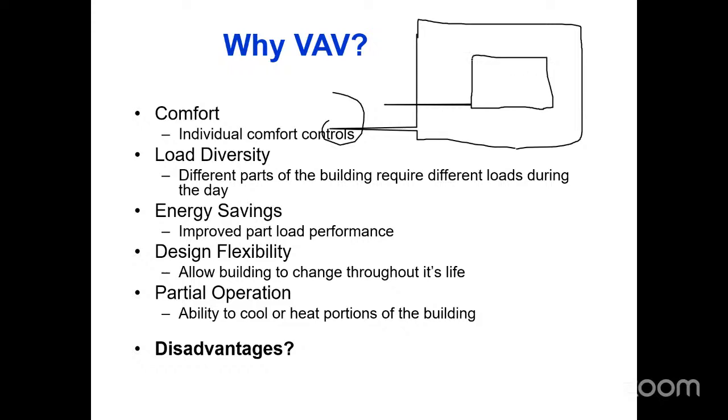The interior of a large commercial building needs zero heating. It does not need any heat. If everybody around it is 72 degrees, the perimeter, in other words, and by the way, the perimeter could be physical walls, or if it's not, you can just estimate it being like 15 feet from the exterior wall or so. It'd be where my core starts and my perimeter ends. Once you get that far into the building, this wall being cold has nothing to do with what's happening in the middle here. So if all four sides of me are 72 degrees, and the floor above me 72 and the floor below me 72, the people in the middle do not need heat.